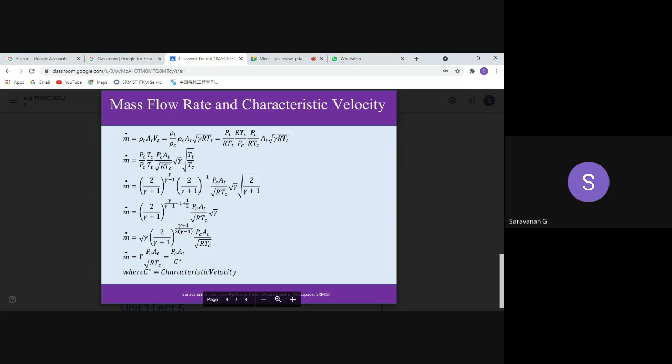So if you go for the isentropic pressure ratio in terms of temperature ratio, the power of gamma by gamma minus 1, that is the second expression. There you would use two equations. One is the steady flow energy equation. The other one is what I call the isentropic relation. Use these two relations and do some simplification steps, multiplying and dividing and grouping or arranging, to get a formula relating temperature ratio and pressure ratio.